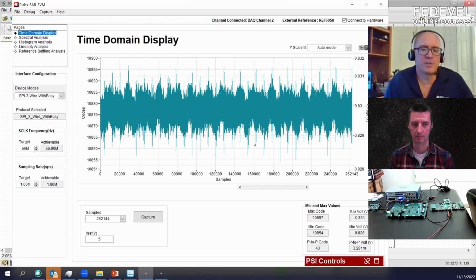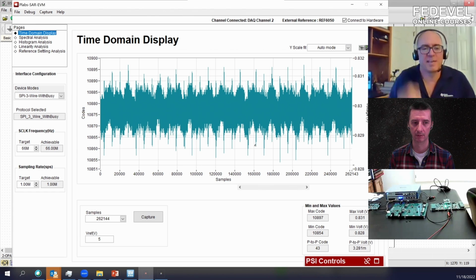One way that you could minimize noise in that case is sometimes there are digital filters. So we talked about analog filters, but the A to D converter itself can have a digital filter, and it may have a notch at 60 hertz or 50 hertz, depending on the region. And so you mathematically remove the 50 hertz from the signal? Yeah, exactly. You'll just notch it right out. And digital filters are pretty flexible. You can have different kinds of digital filters that will act more closely like an analog filter.